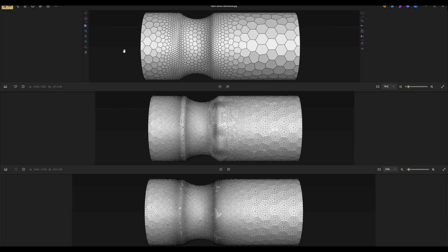Now let's look at the mesh in different stages. This is our initial mesh. As you can see, it's a coarse mesh, and this is the mesh after refinement during the steady state simulation. Most of the grids are divided into smaller grids, depending on the gradient that we had in the simulation.